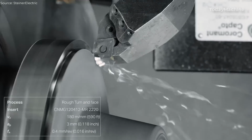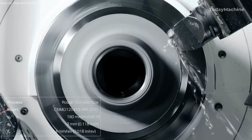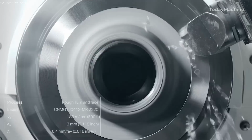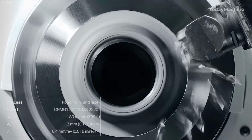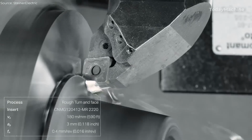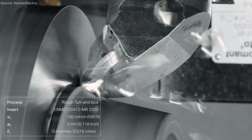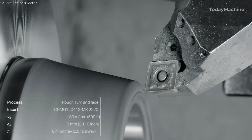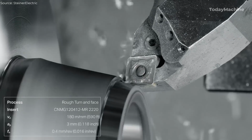The GC 2220 turning inserts are specifically designed for stainless steel machining, offering remarkable resistance to plastic deformation, which is crucial in maintaining tool integrity during demanding operations. This turning grade is particularly well suited for stable machining conditions, where consistent performance is essential.